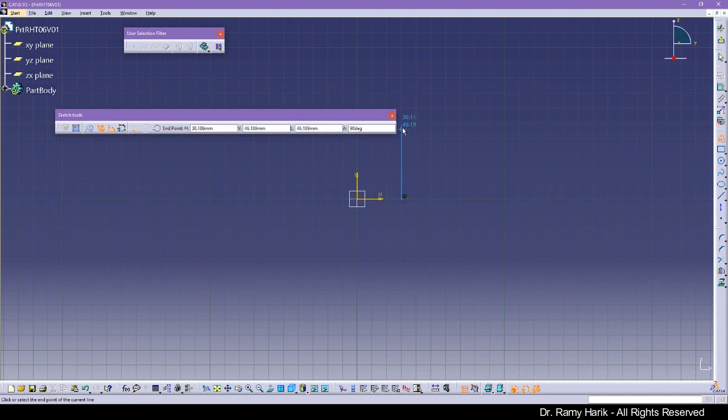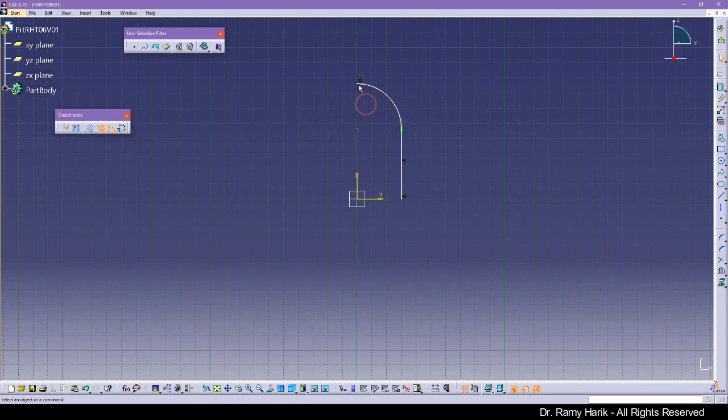First of all, let's go ahead and create a straight line and then a tangent circle all the way till this point. And we can click escape, or if we knew that we're going to end in here, we can double click. I'm going to double click on the constraints so that I create the two dimensions. And now you can see that despite the fact that we have constrained everything, it is still white. It is not ISO constrained.